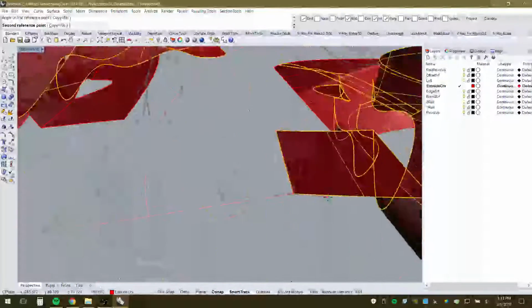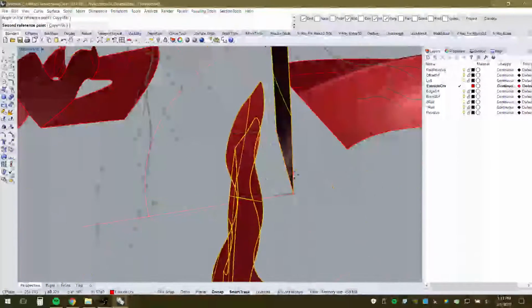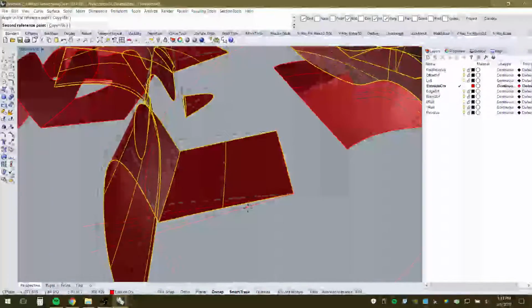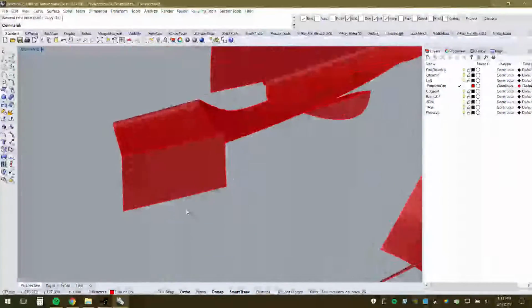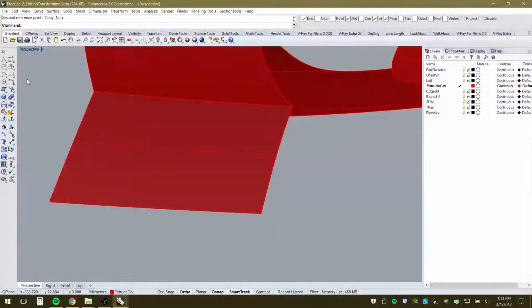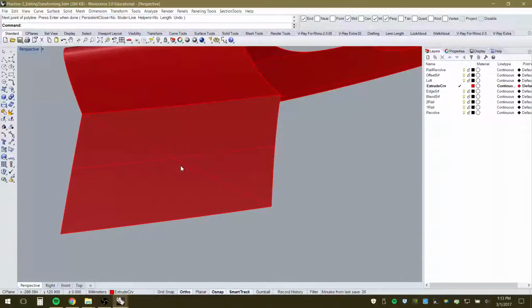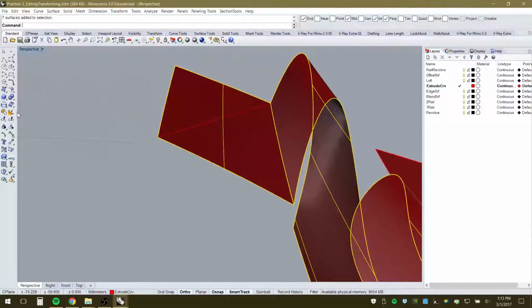And so that's pretty important again when your geometries start to become more complex, or even if you think about the cut and fold technique that we had been working with in the previous exercises. You guys are doing that manually, but in this case that can be done virtually, right? You can fairly easily start to fold things. So say for example I wanted to create a little split on this, endpoint here to corner, endpoint there to corner. Now I have this line, and I can split this surface if I explode it. Explode it again. Oh, it's grouped. So I have to ungroup it.